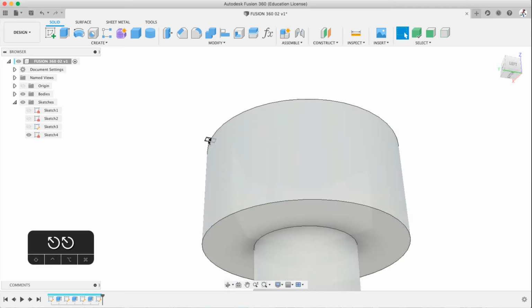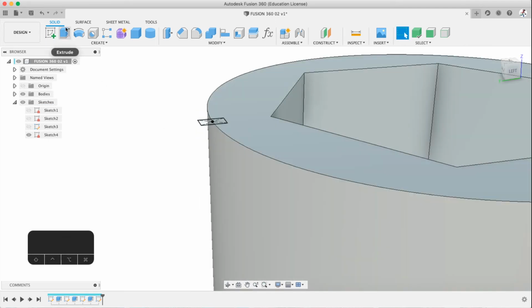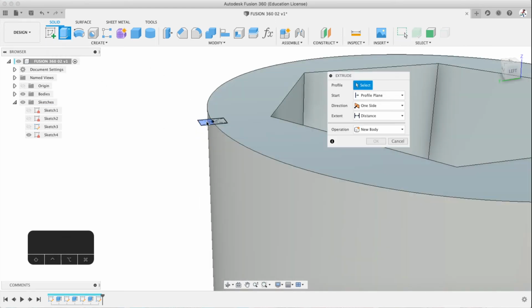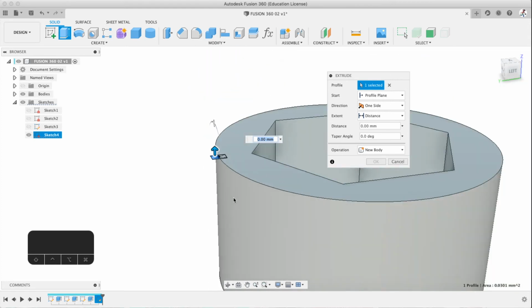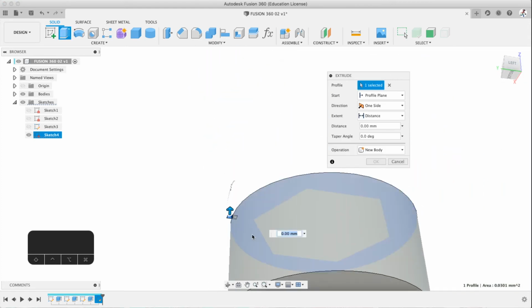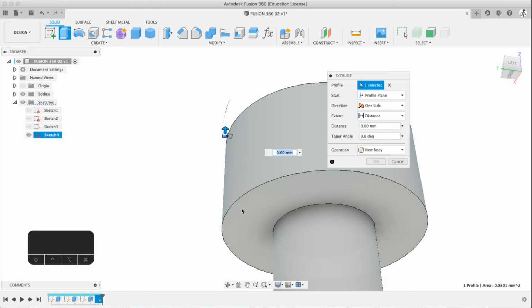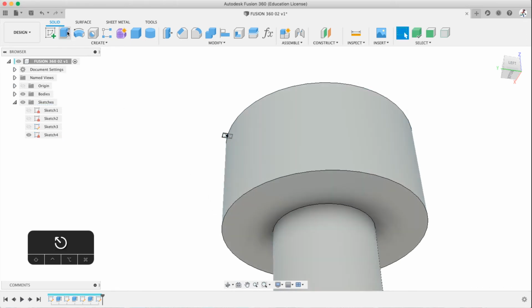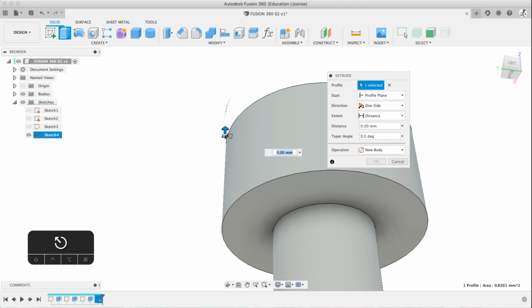Okay, everybody hit escape. Go back to Extrude. Select that same thing. Don't change anything. Don't type in head height. And let's see if it works now. Yes, it's highlighting. There we go. That's why. You just have to reset it. Hit escape is the reset. Select it. Now watch. Click here. It will pull it down right to there. Exactly as it is. So that's sort of a quick thing to do.